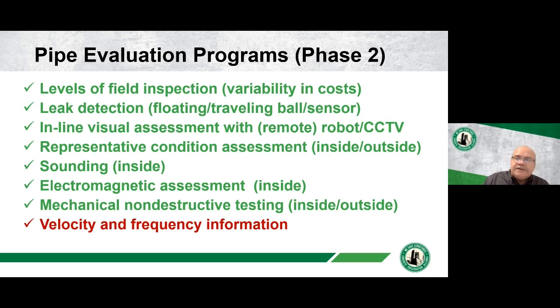We're talking robots, closed circuit TV, even sonar imaging to identify visibly what the pipe looks like and how it is performing. Now, a more detailed approach is a condition assessment. What's the integrity of the concrete pipe itself, whether we're testing from the inside or from the outside? Sounding it, just kind of hitting it with a hammer, or in what I'll talk about a little bit more here, is non-destructive testing. There's also some electromagnetic assessments that can be done from the inside, and the mechanical non-destructive testing is what we're going to do a little deeper dive on here this afternoon.